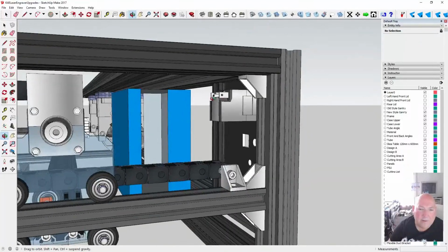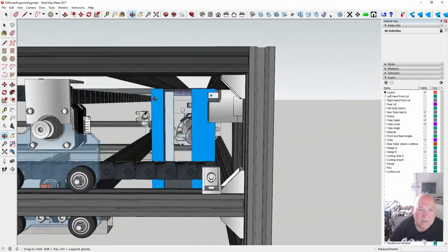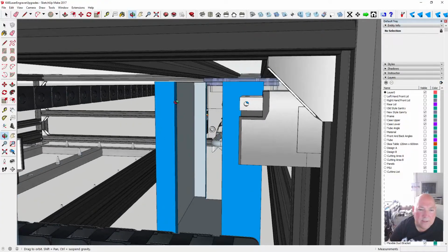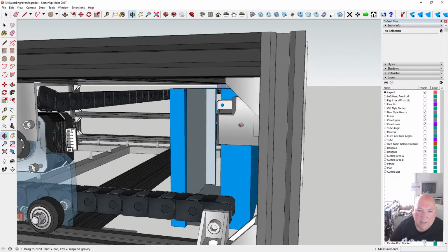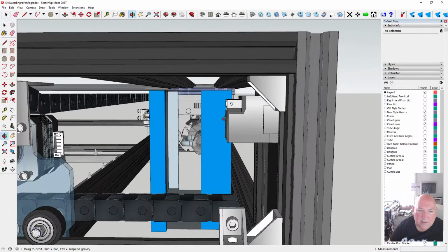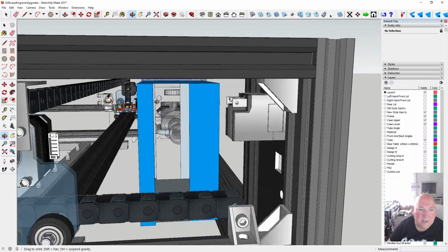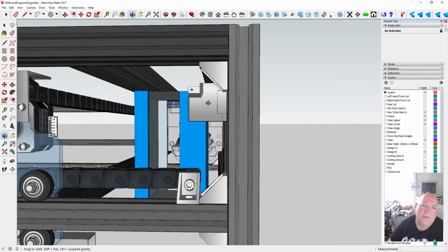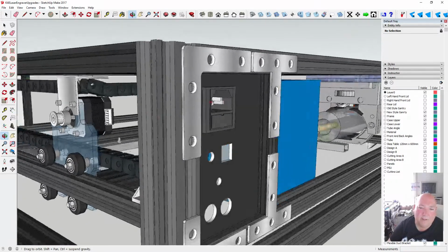And your earth strap comes straight from there to the terminal on the plug. Because this metal case is bolted to the chassis, I've measured it, so the earth is connected to all the steelwork, and this plug has got steel all around it, so it touches this as well.